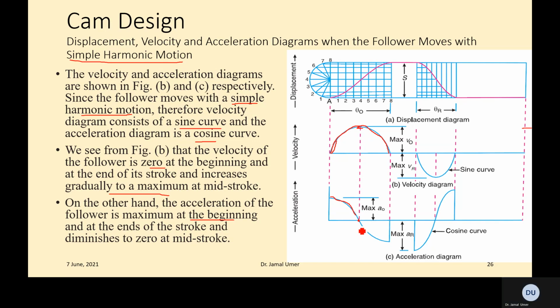Now, you see, this has a certain magnitude. This is the maximum velocity. You can determine this magnitude by calculating the height. For the maximum acceleration, we have acceleration maximum at the beginning, and that's the reference. That's the zero, and that's the maximum acceleration. This graph is quite interesting because the forward stroke has been following this way, but the return is not the same. That's why the velocity profile is also different, and of course, the acceleration is quite different as well.